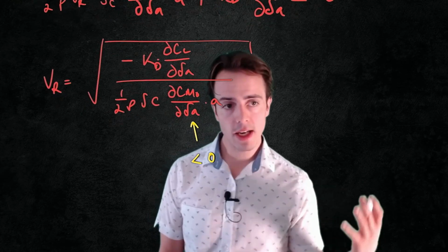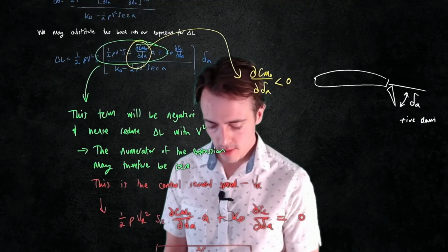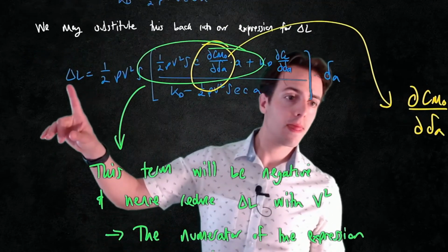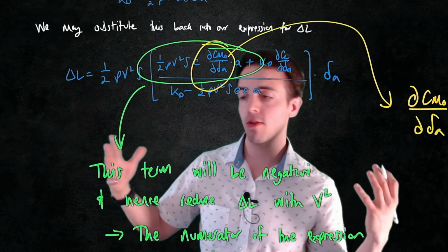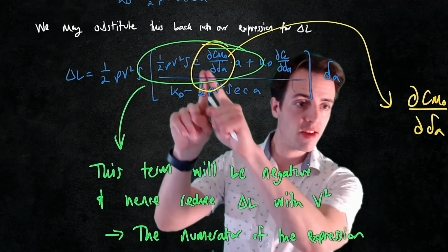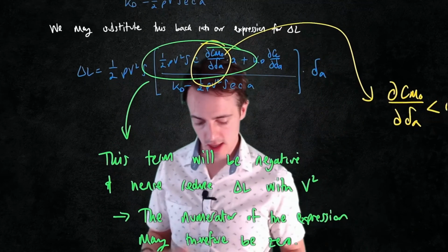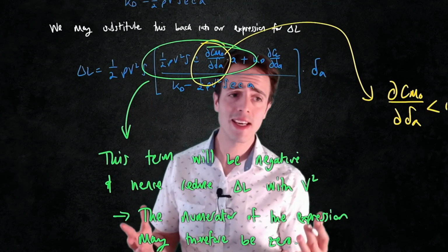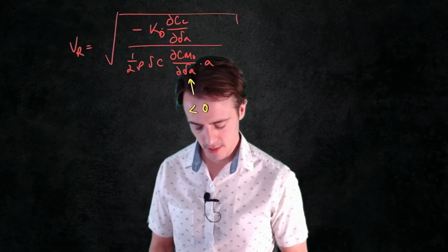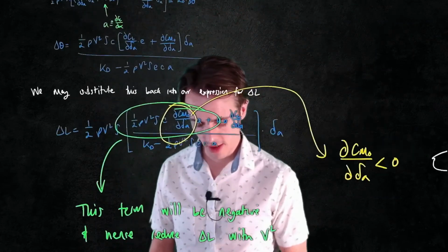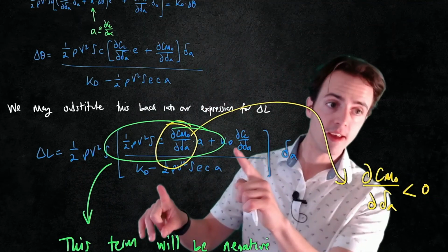We can then define the aileron effectiveness as a measure of effectively how much additional lift is generated compared to the rigid wing. Okay, so if this expression weren't in here, that would give us the actual additional lift given by the rigid wing. In fact, it's not just if that term wouldn't be in there. Let's say it would be if KD was equal to infinity. Okay.